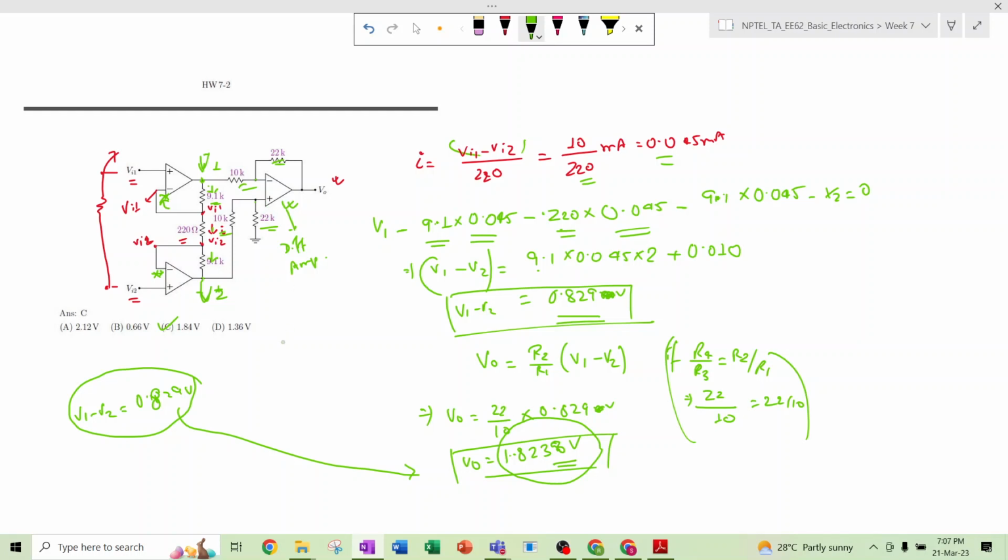That means if suppose there is a pressure sensor, if there is some change of pressure, we convert that pressure into a change in the resistor value, and as a result some differential voltage will be generated, and this small deviation is enlarged using the amplifier and comes in the output, and according to this we can measure and control that pressure.